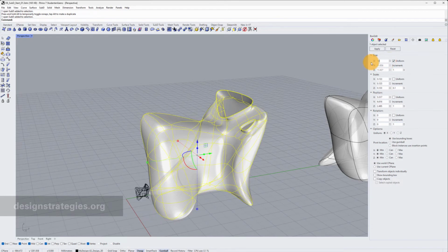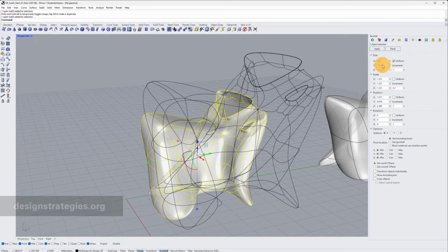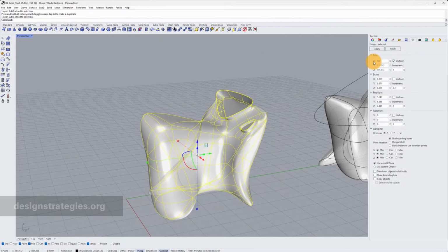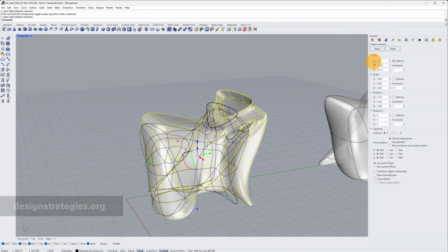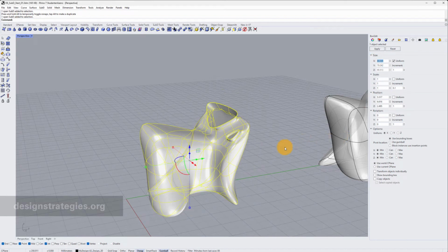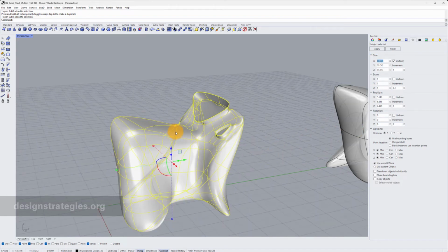For example, if you have something which is too big, like 12 centimeters, via millimeters you can just enter 80 millimeters, and it just shrinks down. And this is a really good tool to adjust your 3D object in any circumstances. I just press my enter key, and this is the size I would like to print it.